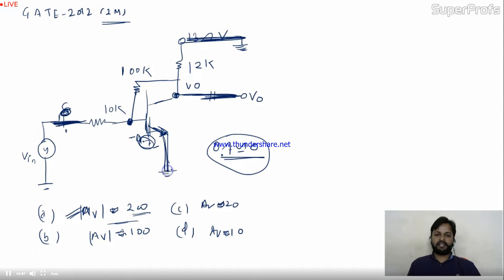Now this is directly connected to the ground. So over here I have 0 volt. This is approximate, not exactly 0 volt. The exact value will be 0.7. Let's take it as 0 volt. Now you have to apply KCL, node analysis, over this node A. Wait a minute, let me clear it. So now you have point A. At point A you have 0 volt. This is an approximation because the exact voltage over here is 0.7 volt.